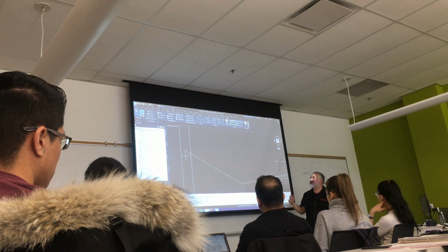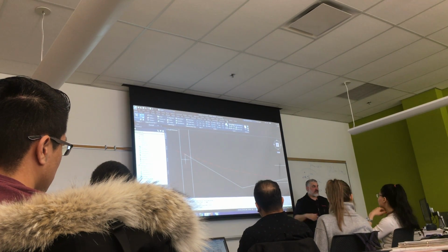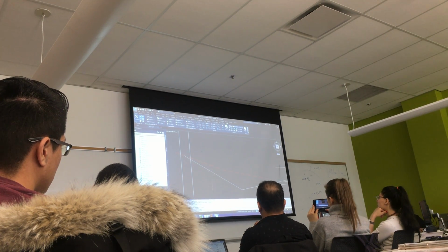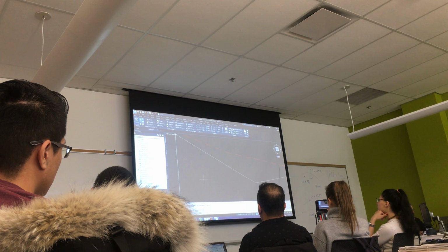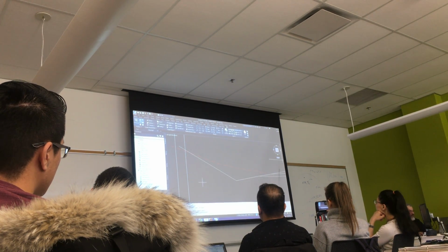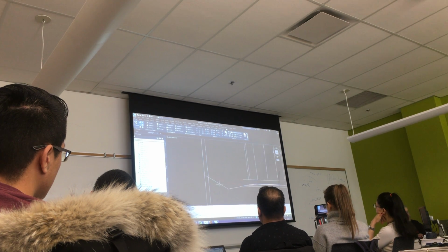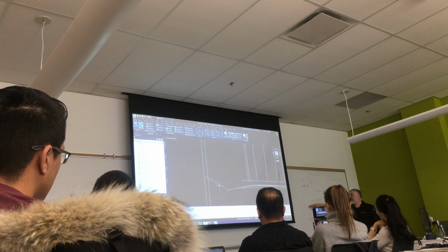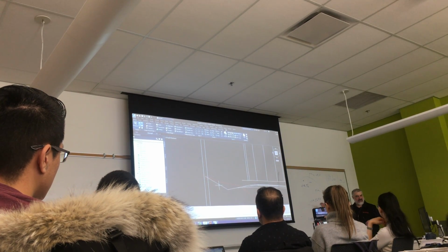What do you do to fix this? You want to raise the cross section so that it ties in sooner, right? We could do this. I could move this, right, the entire cross section. I could take my entire design and raise it until I know it works. But when you do that, you're changing the centerline elevation, which means you're actually changing the design of the profile. If you raise this elevation, you're changing the profile design. Okay? So this is a little bit of back and forth.